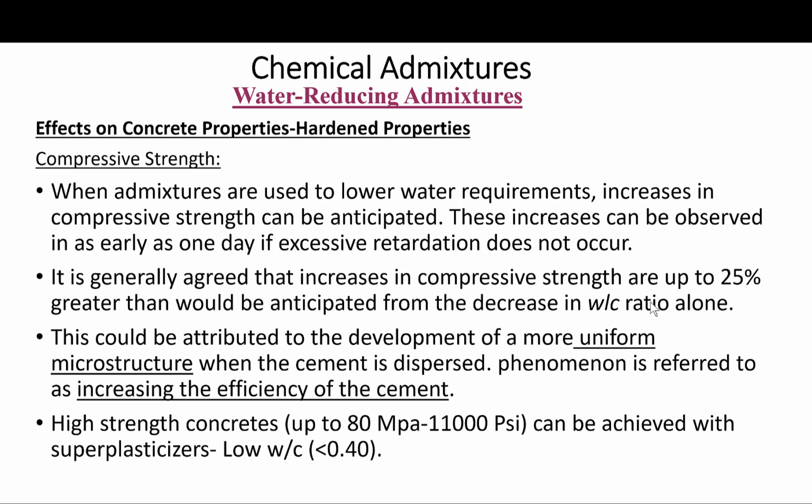And of course, if at the same time we also lowered the cement content, not just the water content, we may not achieve the same strength level, but we did at least reduce, for example, the heat of hydration or the rate of heat generation. And also, when you reduce the cement, you reduce the paste content, and that automatically will result in other advantages, such as the reduction in shrinkage eventually. Remember that.